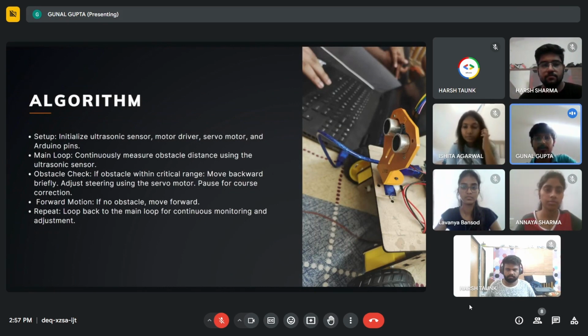The signal gets reflected back when an object comes in front of the sensor and it is received by the receiver. So the same thing would happen in the main loop, and the ultrasonic sensor generates high frequency sound waves and evaluates the echo that reaches back to the receiver. So by using this technique, the ultrasonic waves calculate the distance between the car and the reflected object continuously. So as soon as the obstacle detection is made, the car changes its direction by making an autonomous decision. It can measure the distance between itself and surrounding objects in real time, and the same can be fed into the program using the repetitive loop. So let's see the working model of it.